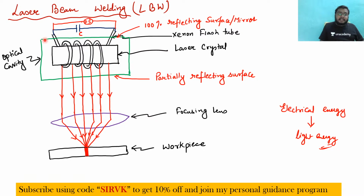And see, this part is a 100% reflecting surface. So whatever photons are being produced here, even if they want to go to this side, they will get reflected back, because this is the total 100% reflecting surface. This other surface is the partially reflecting surface, so some of the photons in the form of light energy will come outside. When they come outside, we use a focusing lens, and with the help of that focusing lens we focus it on the workpiece, and hence we get welding.